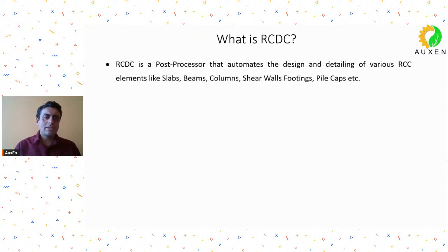So what is RCDC? RCDC is basically a post processor, and the role of RCDC is mainly to automate or do the design and detailing of various RCC elements. Per se, it will not do analysis on its own. Please remember, RCDC is not an analysis software. It is a post processor.